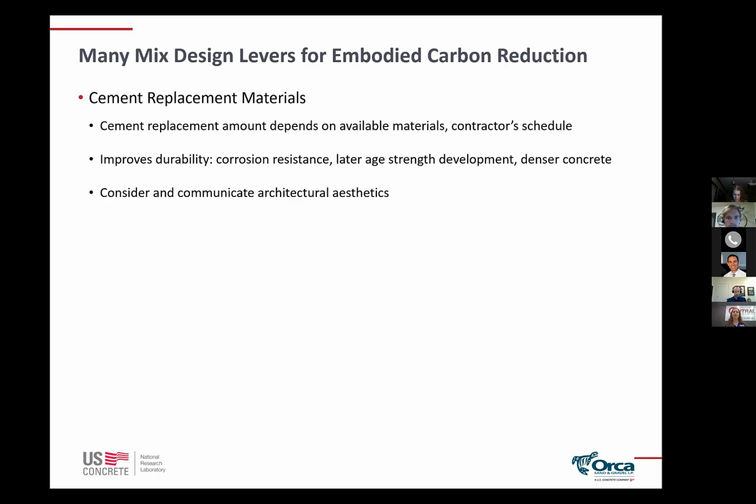Then in terms of cement replacement materials, another term for this would be supplementary cementitious materials, talking about things like slag and fly ash and things that have already been discussed. With this, the cement replacement amount is going to be dependent on what materials are available, because, as John touched on, they do have different properties and are going to give different structural performance to the concrete. And the contractor's schedule is also very important here when you're proportioning a mix design.